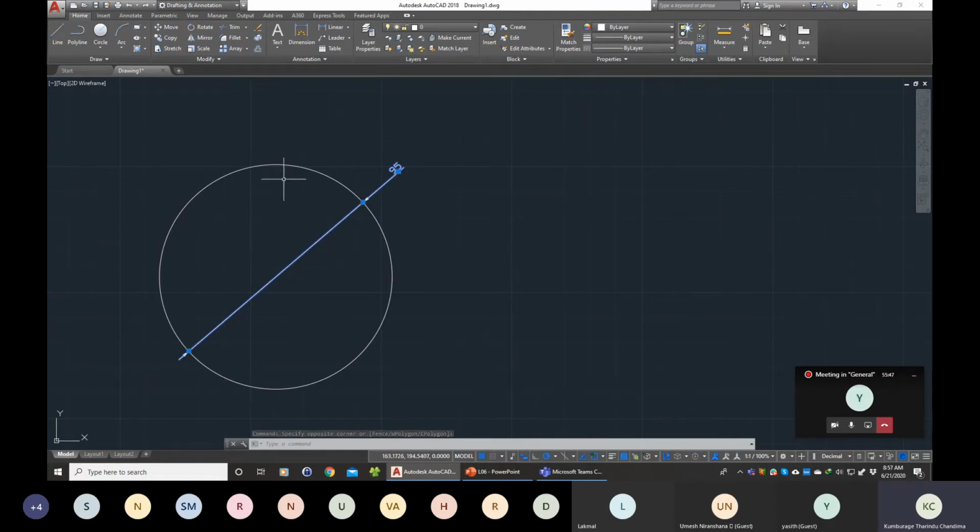When you draw in AutoCAD, do not just draw it in an arbitrary value and rename the text of the dimension as your preferred value, right? It will confuse the manufacturer. So this is the case in earlier versions of AutoCAD.